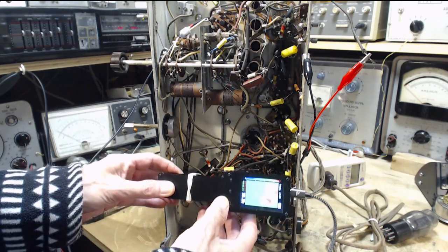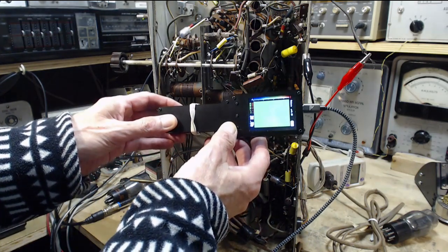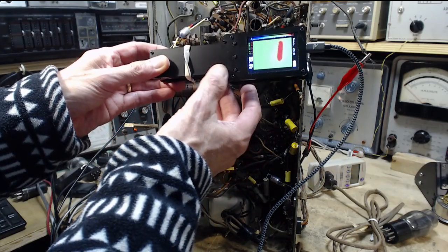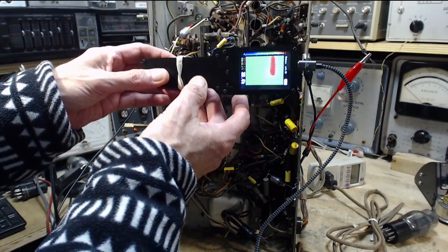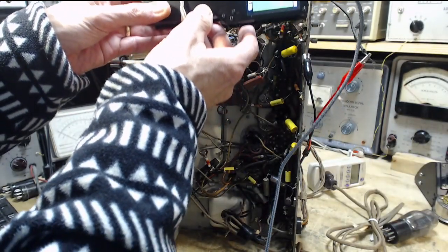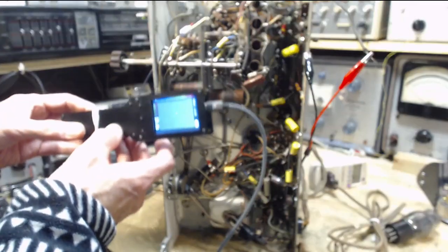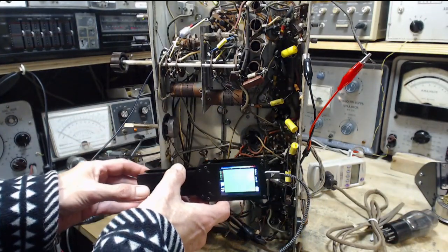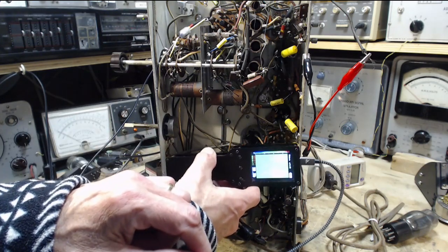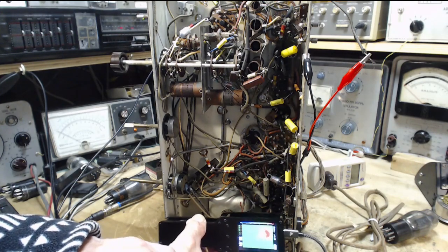And okay, any more heat in here? Why would these sockets show up so hot when none others do? Okay, and that's that resistor, 62. So the two high wattage resistors are cooking away. All the other tube sockets are showing just a little bit of yellow on the screen here. It's probably not even visible. Why is this guy so hot? Is there something more going on down here?